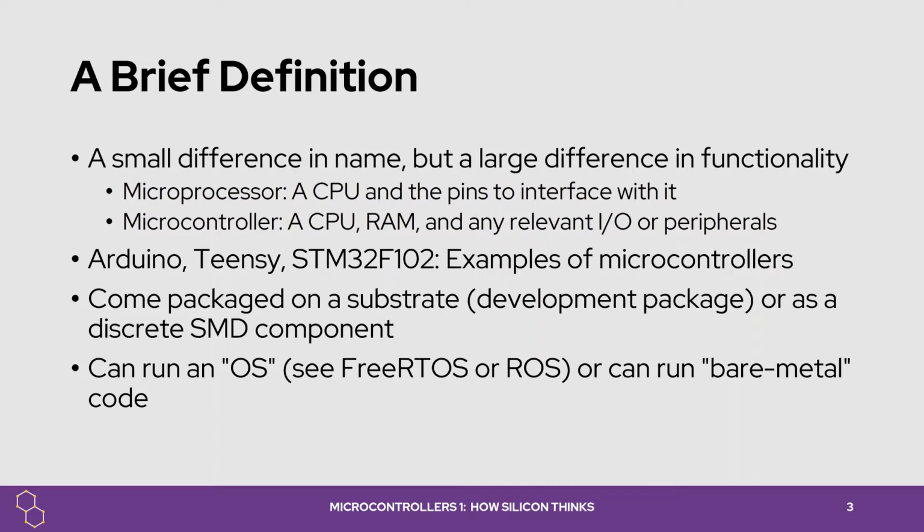Whereas SMD components are more for finished products, where you burn the program using an external programmer, and once it's been burned, you don't touch it, ever really. When you've got a microcontroller, it can either run a so-called embedded OS, or it can run bare metal code. The difference between the two will be covered later by Hakan.